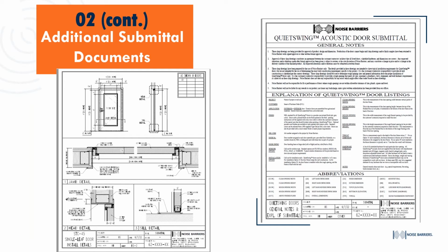In this case, it shows a nail plate on the jambs with the drywall coming over to cap that nail plate. And it could be a three-sided, a 3 sheetrock one side, 2 the other. It could be a masonry opening. It could be an isolated wall. Whatever that is, we take the partition detail from the project and transpose it onto this page so that it's ideally a perfect match to what the real wall is and then how the real wall will be framed out. And that gets addressed again in this installation video at the end.